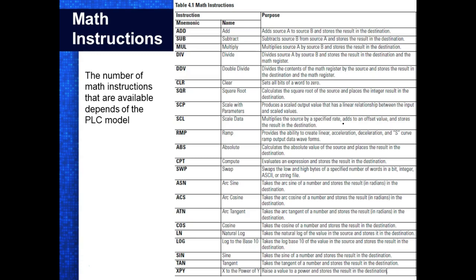We do ramps. Ramp is basically something we used to do to control DC drives. We call them SCR drives, which required a ramp to actually control them. Also, we use most variable speed AC drives. They call them variable frequency drives, but you have to do more than vary the frequency.